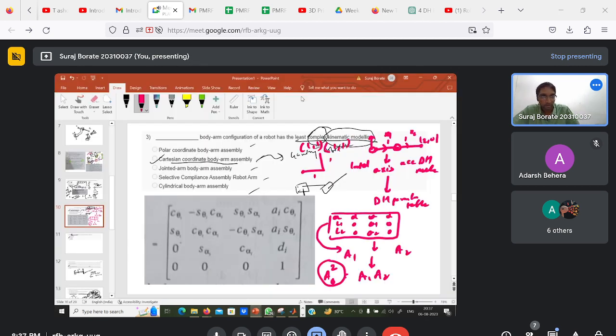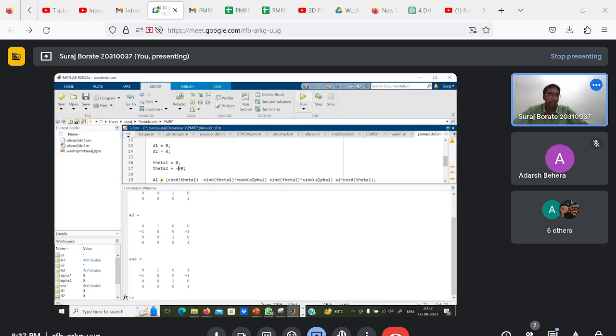If the rotation was about minus 90, it would look like this. So this direction is minus 1. So the coordinate is what? 1 comma minus 1, right? So this works, right? Whatever we did is working, and this is the forward kinematics, because why? We change the angles and we get the end effector position.